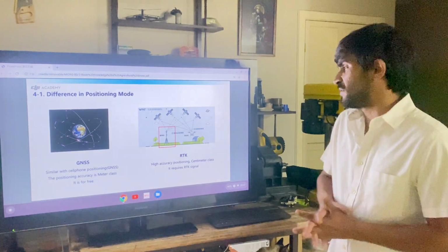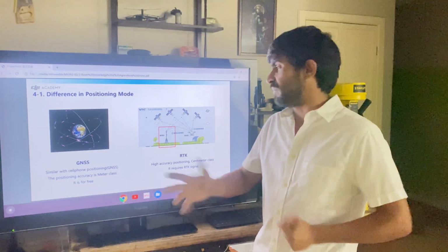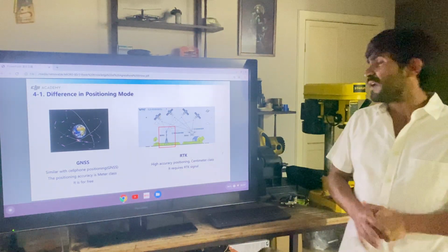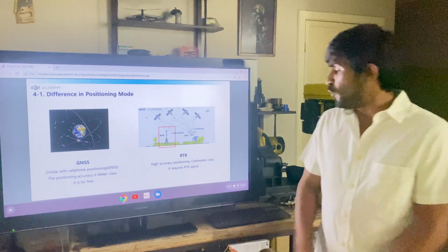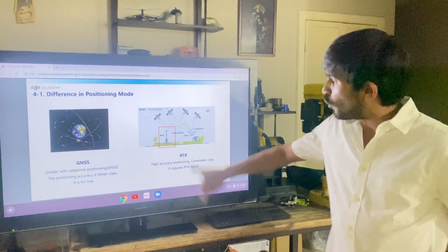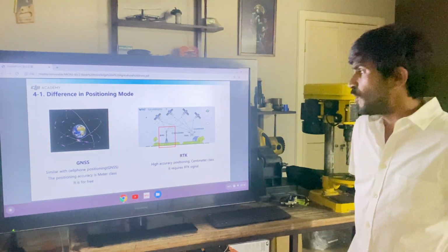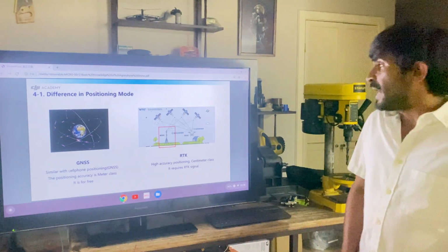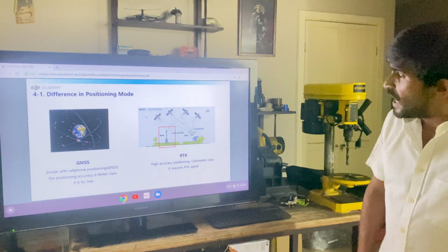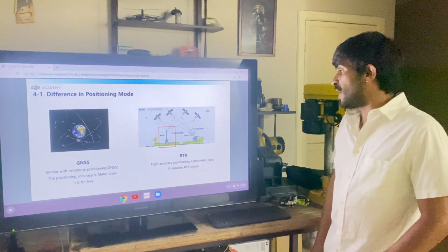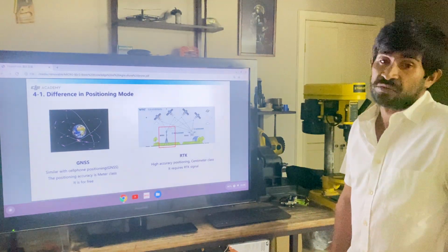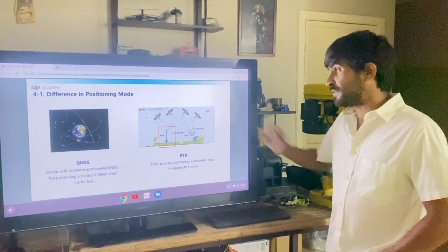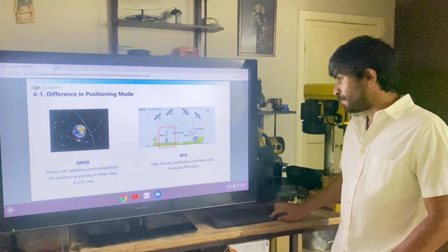Even if there are small drifts, it will normally be no problem unless you have obstacles, right? And some people do want higher accuracy. They can use RTK, real-time kinematics. You need the drone, the remote control, and also an RTK base, which is mounted normally on a tripod. It is a fixed base, it cannot move. And you get really precise positioning with this. Honestly, I've never tried it, but I've heard it's really good. It's necessary for orchard mode. It's very, very necessary for orchard mode, so yeah.